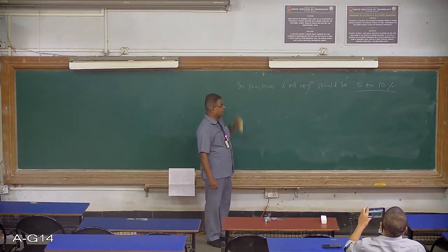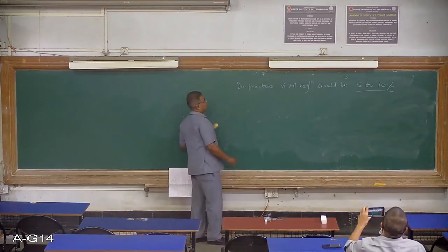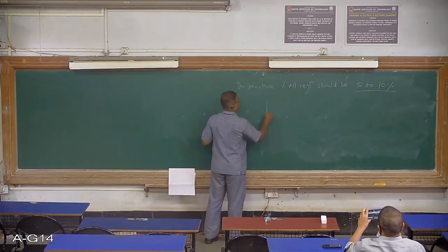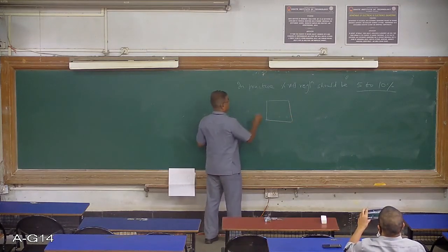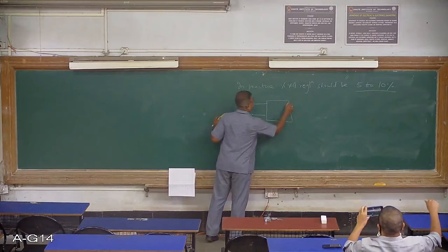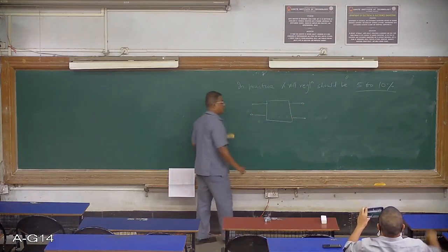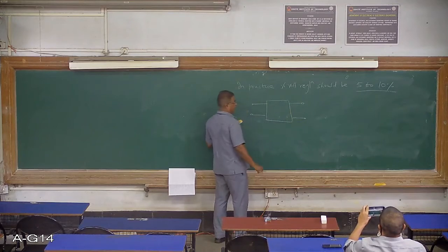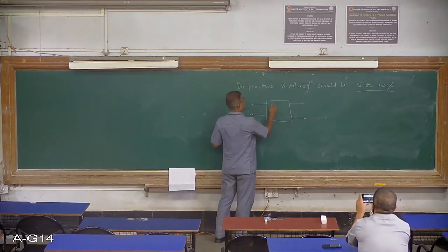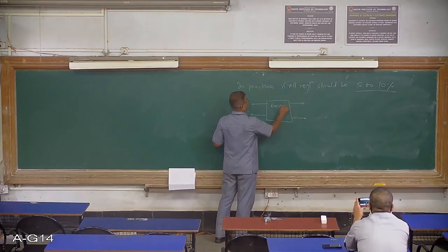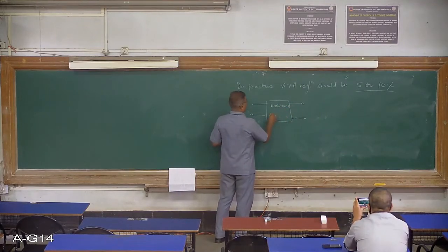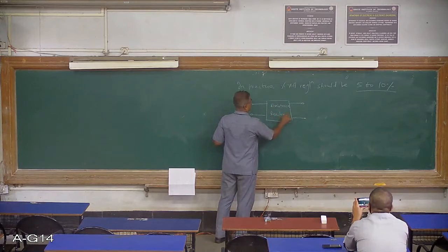So just be concerned about that. And it is worthwhile to know why this voltage regulation occurs. This transformer is an electromagnetic machine. It has a primary winding and a secondary winding. So therefore there will be resistance for the primary winding and secondary winding, and leakage reactance for the primary and secondary winding.